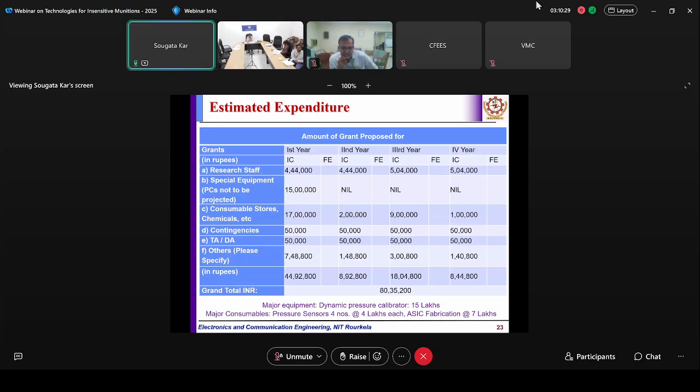Sir, if you want more resolution than 12-bit, how much resolution do you want, sir? 16-bit? Minimum 18, sir. Okay, so then we have to integrate one external ADC to acquire the data. We will not use the internal one, so that is one solution.